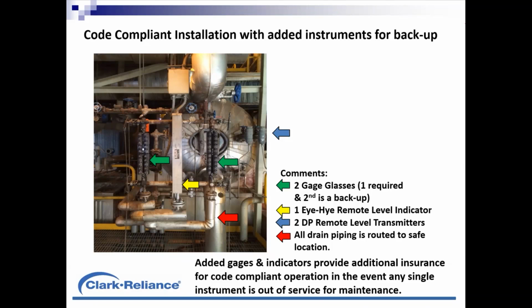And you're vulnerable in either long horizontal runs or elbow turns, right near a horizontal run, sideways turns. Sediment buildup can cause a false level indication on those devices. Check also on any instrument with the OEM for the instrument itself. They would have the most accurate recommendations and maintenance instructions for any instrument on your boiler.